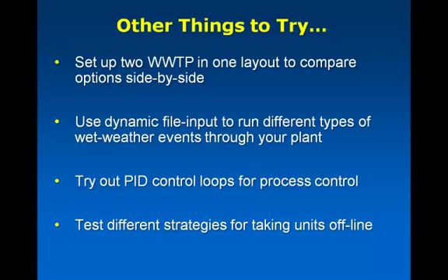Some other things you may want to try with your version of GPSX, just to get a feel for what can be done. Quite frequently, people like to set up 2 wastewater treatment plants in one layout and then compare the options side by side. That's a common use. You have a single influent that you split between the 2 plants, and then you can investigate and compare them nicely and easily side by side under different loading conditions.